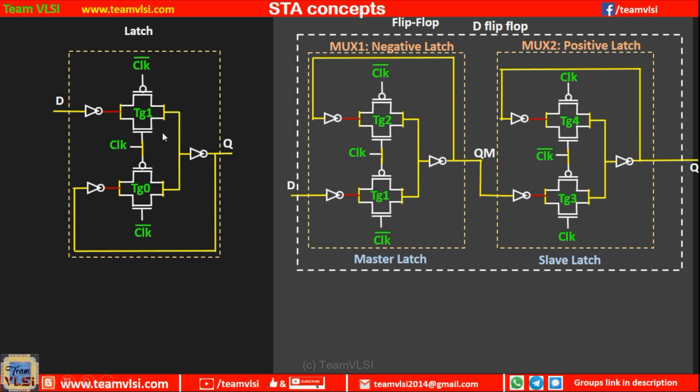So this transmission gate 1 is completely off, but at that moment, since the clock is low, the PMOS of transmission gate 0 is getting low at its gate and the NMOS is getting high at its gate, so both transistors are going to be on. So we can say that this path will be activated, right, and the other is disconnected.